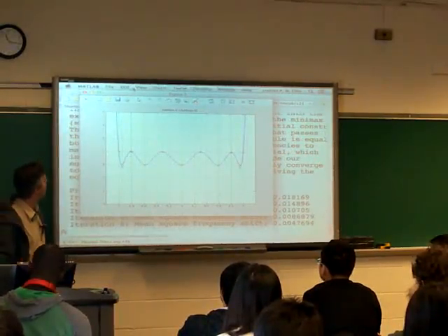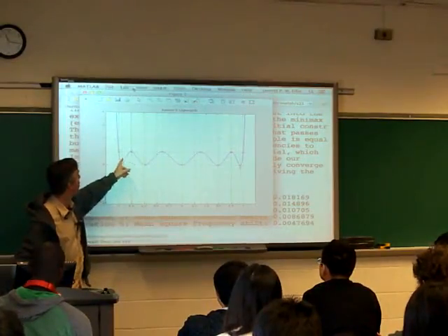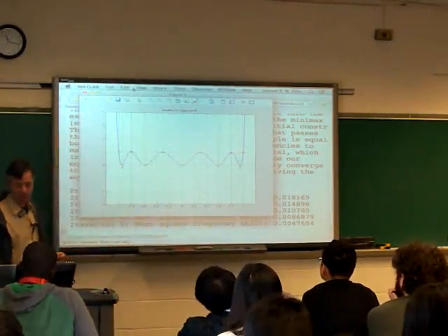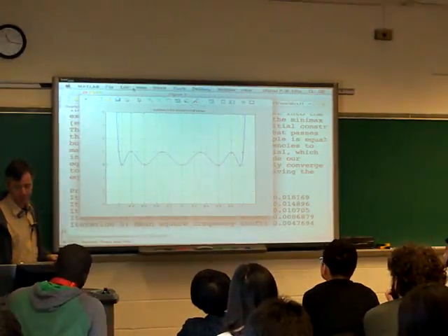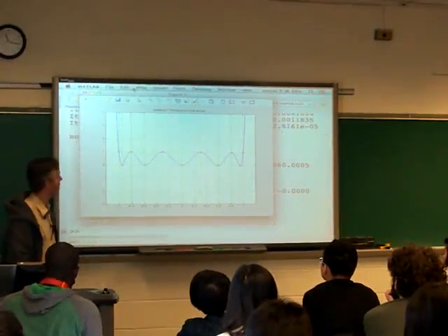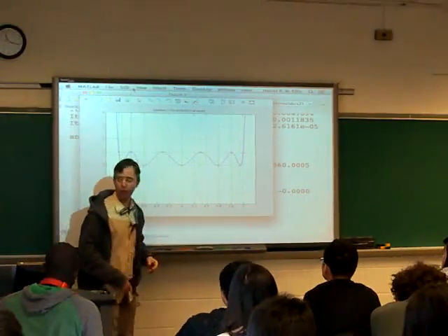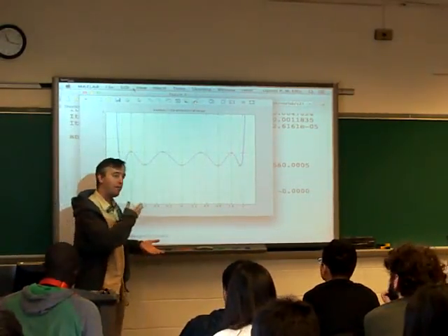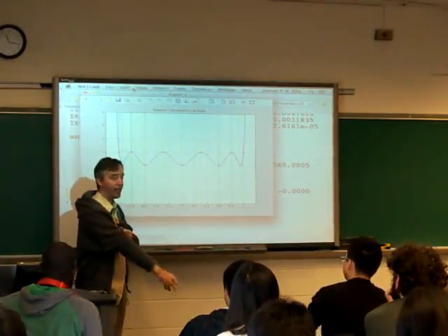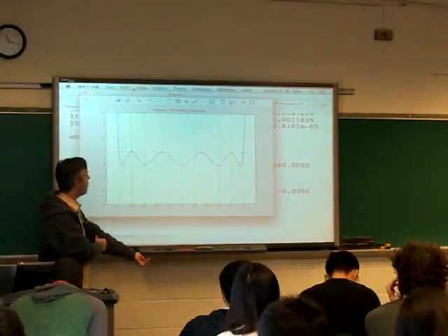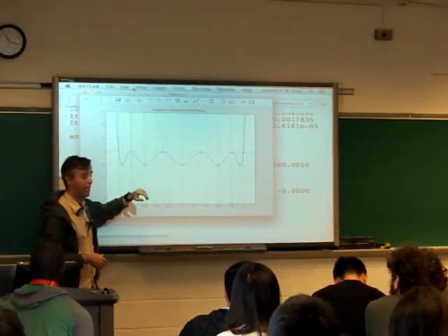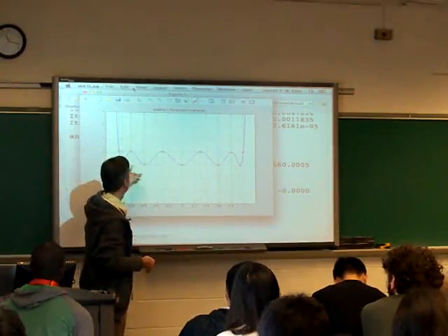And pretty soon, on the 6th iteration, we've now got this polynomial which actually does have this property of being equiripple. Yeah, it just does 7 iterations, but the 7th iteration didn't move it visibly at all. It's only asymptoting towards giving us the best solution, right? It's never finding necessarily the exact right solution. It's just a numerical approach. But for any given level of error, it quickly reaches that error in just a few iterations. And so it does that technique.